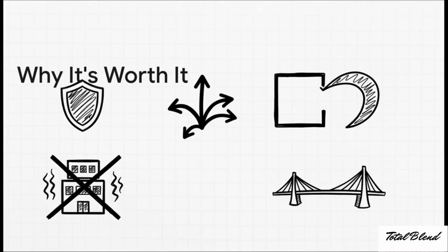And the perks don't stop there. Because the loads get shared more effectively, indeterminate structures can often be built with less material, which saves money. They also tend to be a lot stiffer, which cuts down on vibrations and just makes them feel more solid. All of this gives architects and engineers incredible flexibility to design wild new forms and create buildings with huge open spaces.